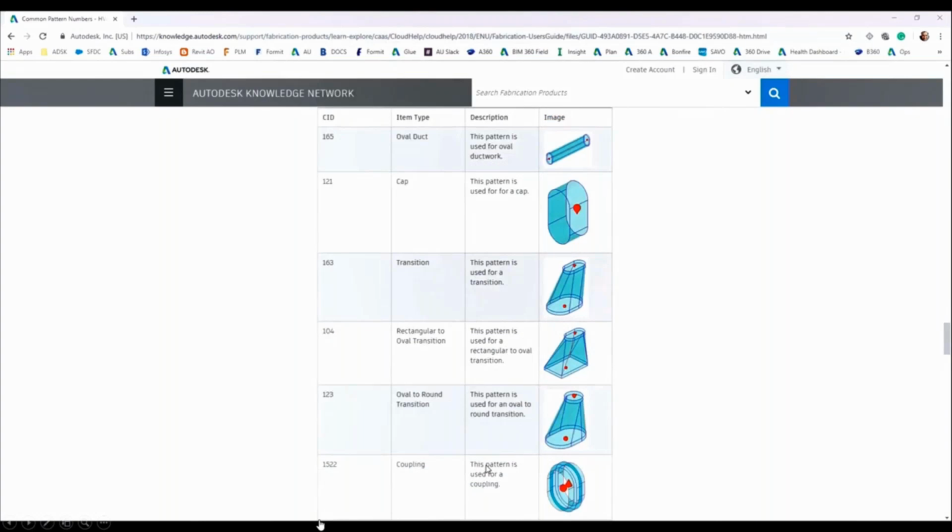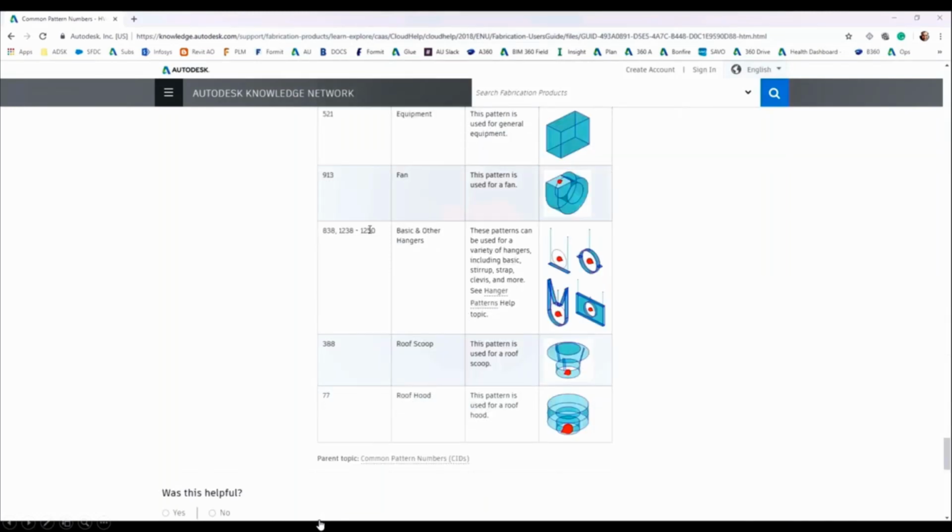Here I'm choosing some dividing junction, a two-way junction. I'm taking it right now here. Maybe I take this, I'll copy this ID and I will go to Fabrication CADmep. This is the default one, which I have already created. Some branch I have created here, for example.